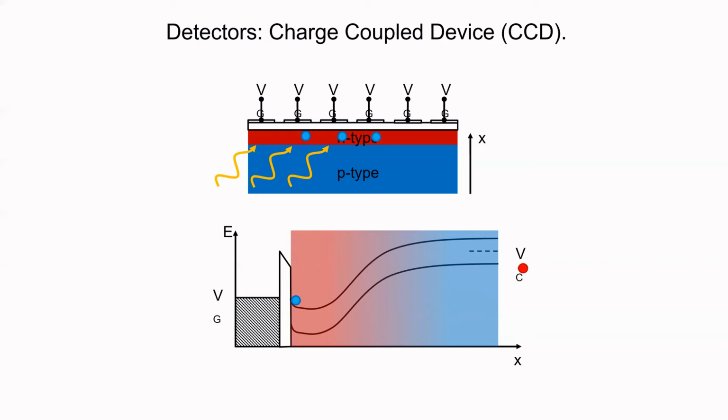And so what you do is you do this sort of shift register type operation where those electrons are moving along. Why is this a great way of doing things? Well, because it's a multi-pixel detector. So now you're able to detect not just that you received some light, but exactly where you received the light as well. And if you build your structure right, you can also encode pixels which will respond to different wavelengths of light. So you're able to get color information as well.